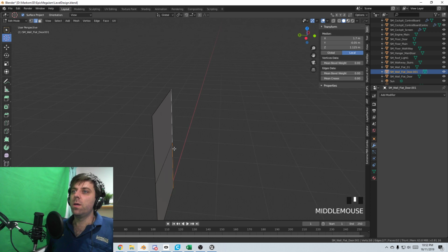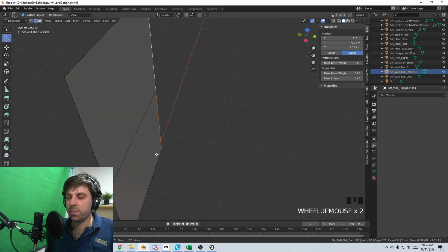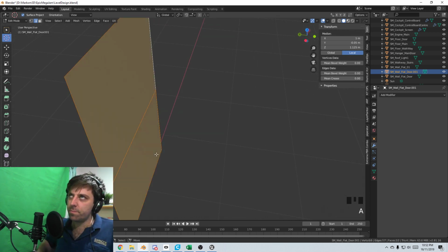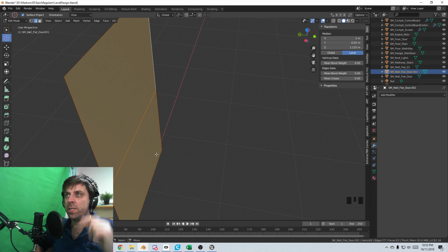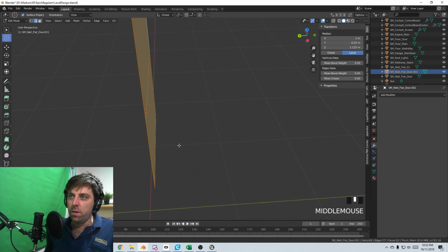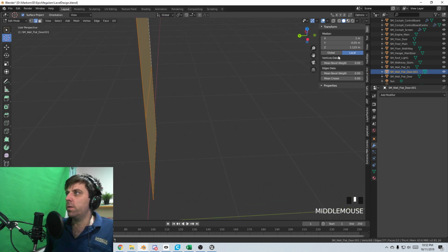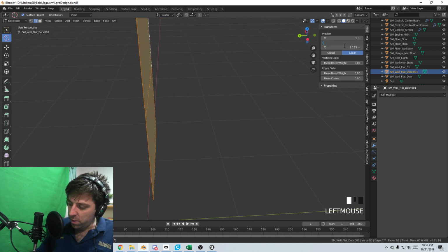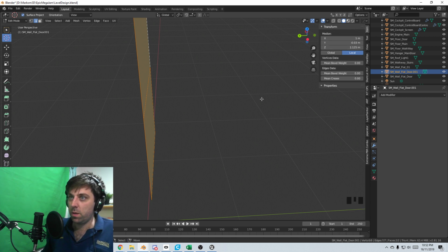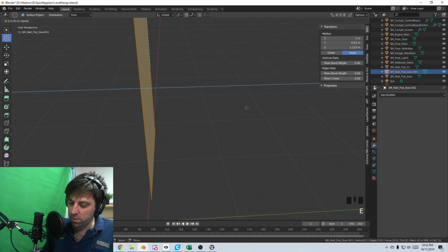Beautiful. From here, I need to make a single door. What I'll do is make a blueprint for Unreal for just the doors. Okay, so minus 0.03. E to extrude 0.06 minus. There we go.